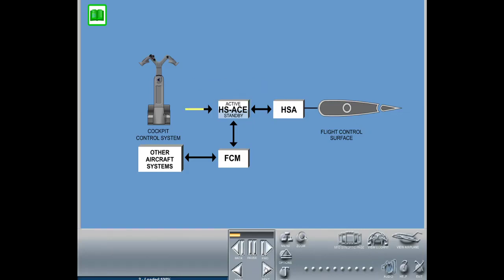During normal operation, one channel operates in the active mode, actually controlling the actuator, while the other is in standby. The flight control module alternates the active standby configuration of the channels following the first power-up each day. Channel 1 is powered by main DC Bus 1, while Channel 2 is powered by DC Essential Bus 2. If an error is detected, the monitor lane will stop the electrical motor, in effect shutting down the channel. As a result, the standby channel then becomes the active channel.